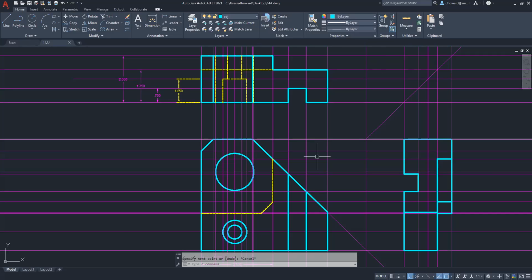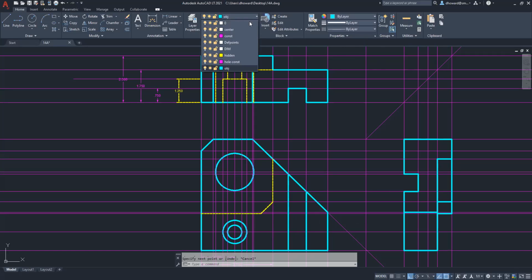So now we can do the hidden lines, and we'll do these holes really quickly. There are no, actually there is an object hidden line. The one, that's this back corner right here. That would be a hidden line showing us where this chamfer is on the back side.